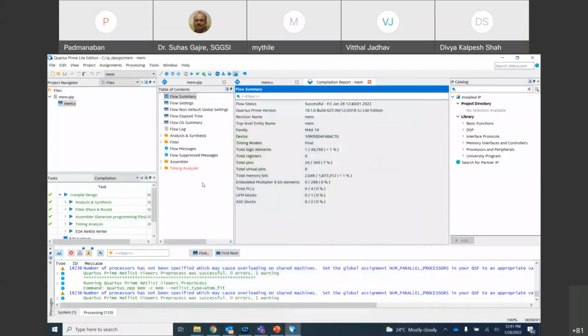Right. So now what we have done is analyzed how to generate the IP and integrate it into your design. But what is very important for us is to initialize the memory content. When we need to initialize the memory content, we also need to add that memory initialization file. It was showing that you add the MIF file. Otherwise, it will be blank, right? So how do we solve this problem? We can definitely create a memory initialization file. How do we do that process?